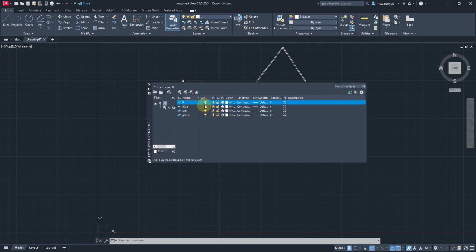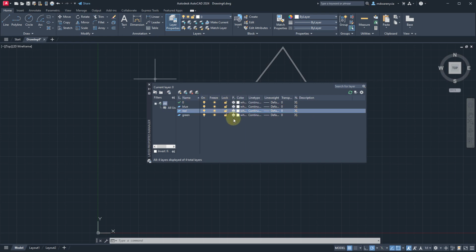But again, don't. So then we have a couple settings here. So you can see if the layer's on, we can turn the layers on individually. We'll do some stuff and then we'll show what's going on there. We have the freeze. And the freeze is specific to viewports. So you don't ever want to freeze anything here when we're in the model space, which is this black area, right, that we're actually drawing in. We'll get into freezes when we do viewports probably next week as well.